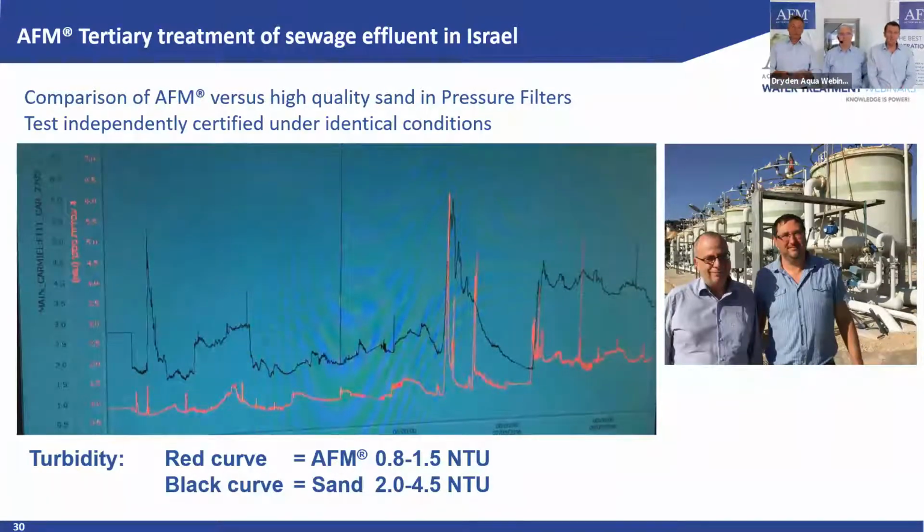Now, there were 2 reasons. First of all, they complained and said, Dominic, the filtration performance is great, but we have to backwash the filters more often. Well, ladies and gentlemen, that's the reality. If you want to filter more, you have to backwash more often. We compensated this by adding the anthracite, and this is where we learned that this increases the backwash times by a factor of 4. Then we were equal to sand. So that was one of the complaints.